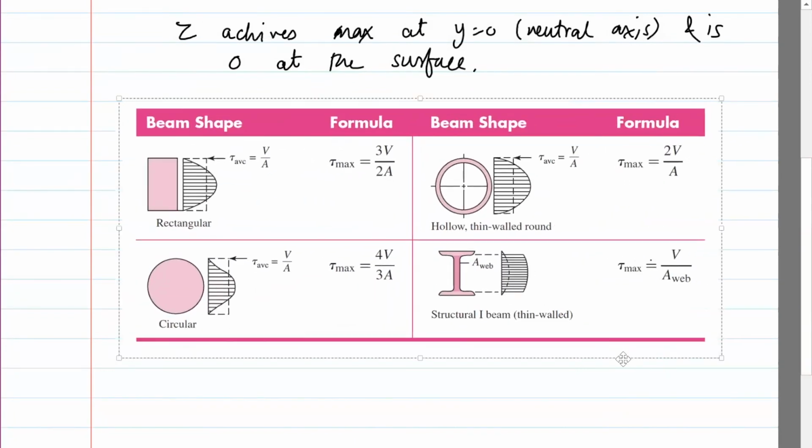It basically gives you shear stresses for different geometries. So we've seen one for the rectangle. It's on the top left. Then there are two more sections which are circular on the top right and bottom left, right? Circular section and an annulus. In all cases, you can see that the shear stress achieves a maximum value at the neutral axis, and it's 0 at the edges.